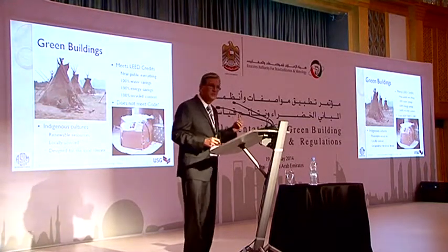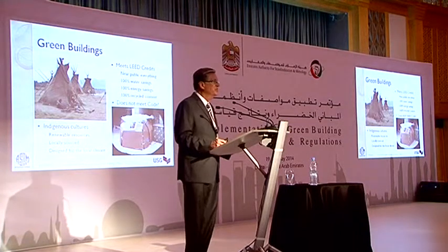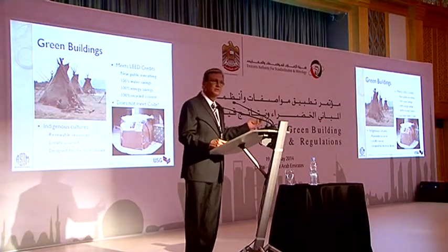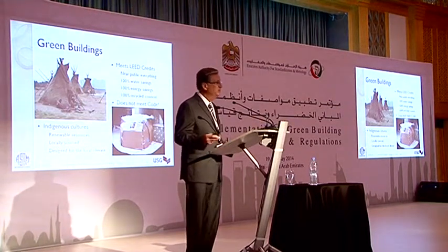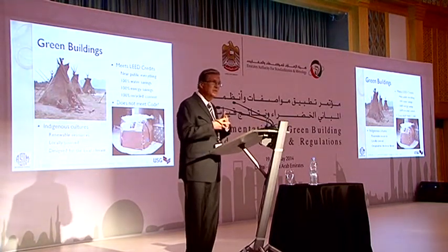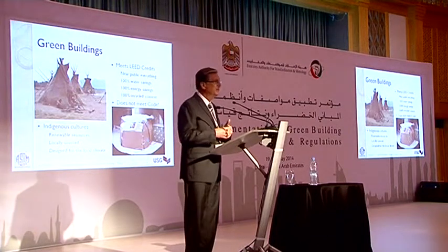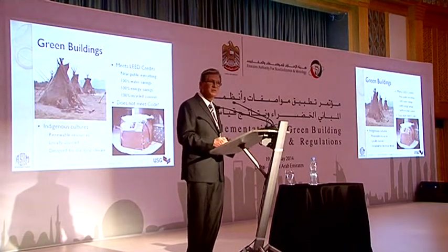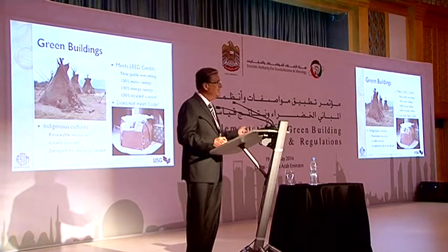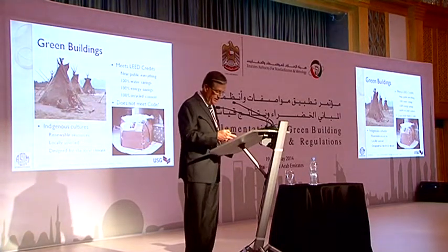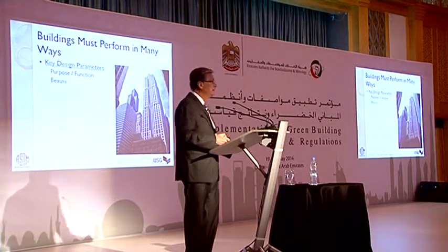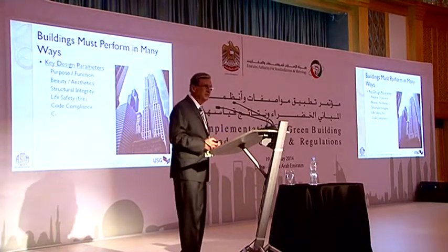And my purpose for this particular illustration is to point out that the green standards do not, and the green code does not, stand alone any more than the building code stands alone. The green codes that are adopted, the energy codes, must be compatible with the building codes and the structural codes so that each of them work together and do not contradict or create problems in designing buildings that meet the performance requirements of the buildings.